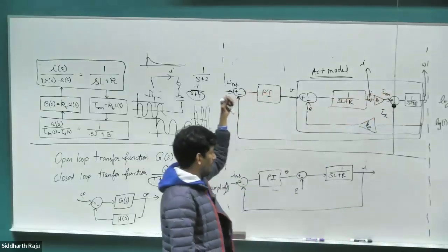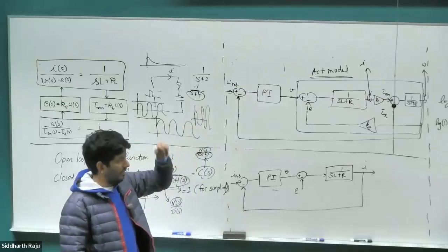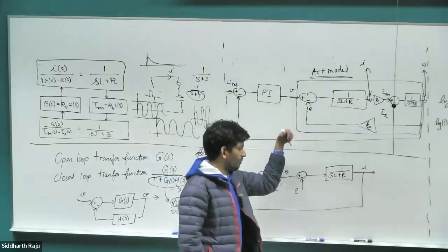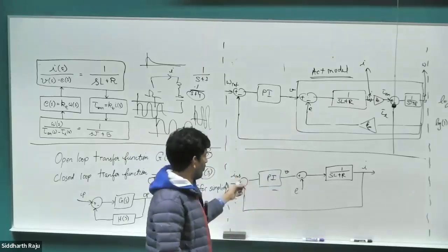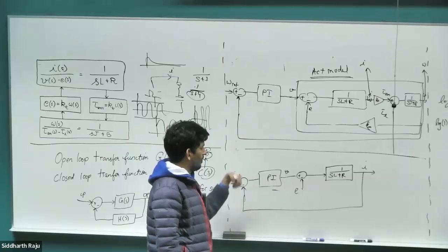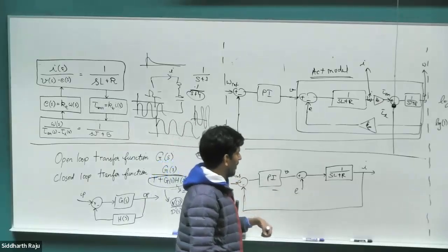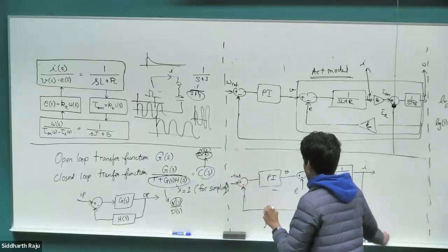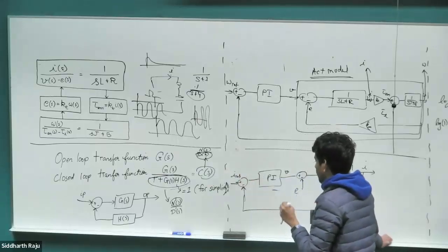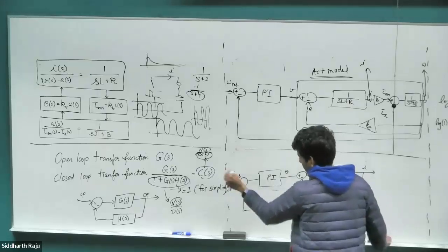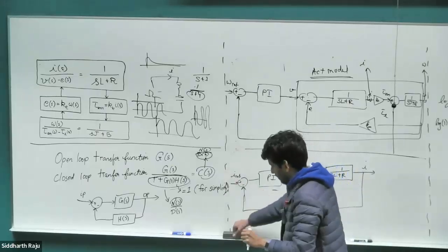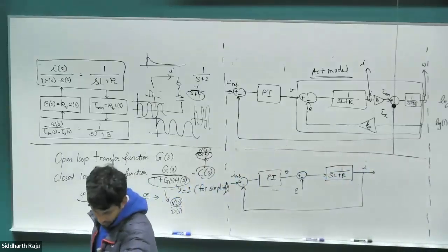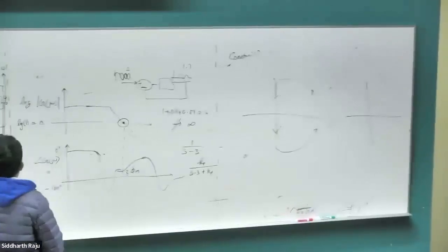And typically in any kind of motor, particularly at low speeds, you would want to do torque control. As you go to higher speeds, you would want to push it to some particular speed and go from there. When you're starting off, you want to have torque control. When you go to some particular speed, you want to have speed control. So there are applications that would require purely torque control on its own. But in our case, we'll extend this further to speed control. For now, let's start off with this current control. Okay, so let's write down the equations for the PI controller transfer function as well.